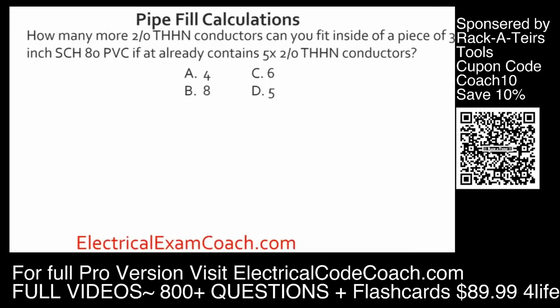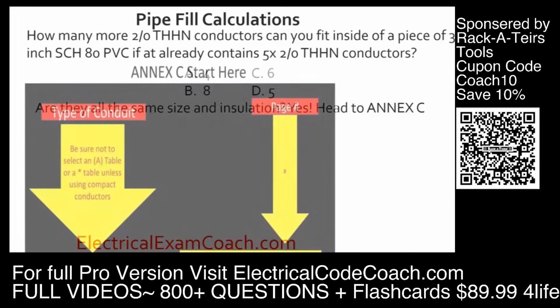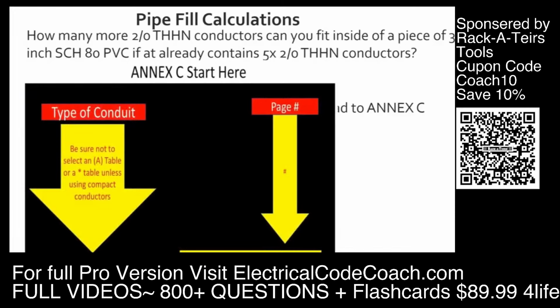How many more 2/0 THHN conductors can you fit inside of a piece of 3 inch Schedule 80 that already contains 5 2/0 THHN conductors? Well, the first question we're going to ask is, are they all of the same size and insulation? Yes, so let's head to Annex C. When we get to Annex C, we're going to start on the left-hand side until we find our conduit, being sure that we're not in the A version of the table. Then we're going to come over and cross over and find our page number.